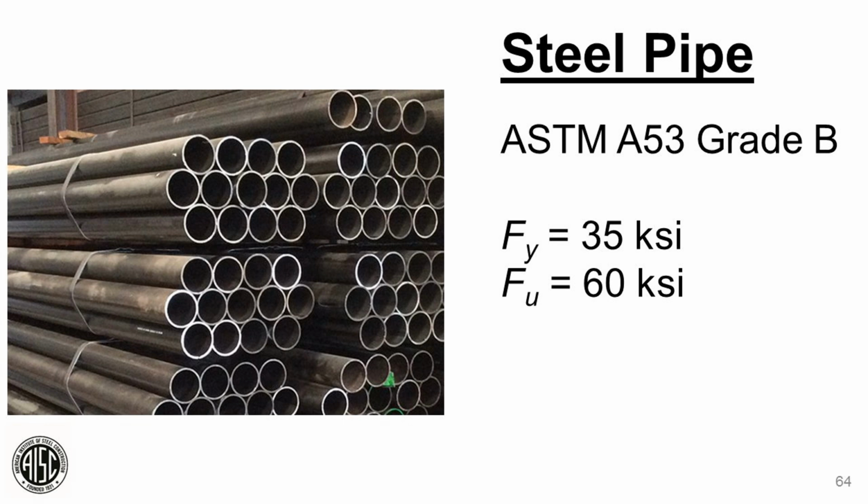It's very common that if you are specifying a steel pipe and it's to be used for a structural purpose, you will probably be receiving an A500 grade C round HSS rather than the steel pipe. The only time it would be critical is if you need to use it for transmission of fluids. And then the A53 grade B is critical to be used. So there really is no advantage for a structural purpose to use steel pipe.